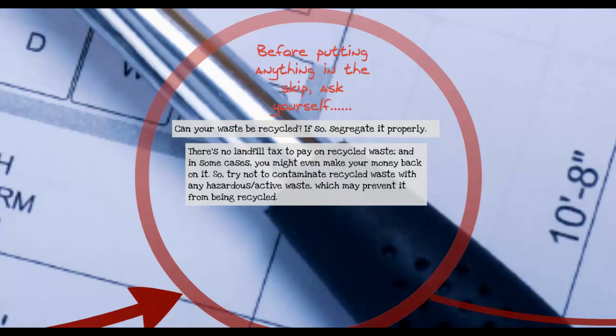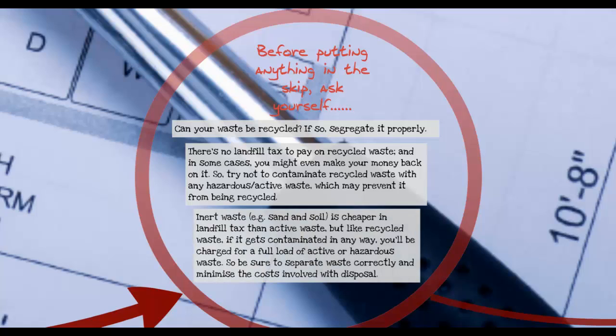There's no landfill tax to pay on recycled waste, and in some cases, you might even make your money back on it. So try not to contaminate recycled waste with any hazardous or active waste which may prevent it from being recycled. Inert waste, for example sand and soil, is cheaper in landfill tax than active waste. But like recycled waste, if it gets contaminated in any way, you'll be charged for a full load of active or hazardous waste. So be sure to separate waste correctly and minimize the costs involved with disposal.